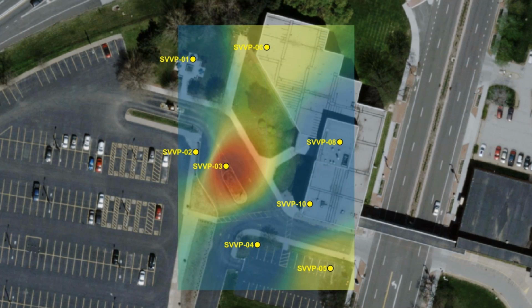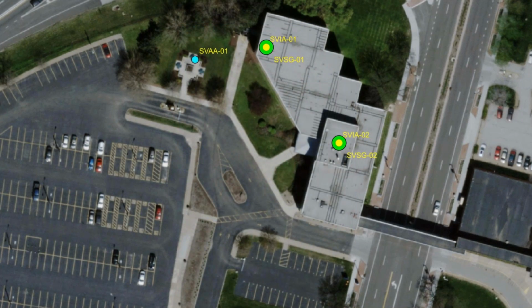They decided they wanted to collect some indoor air samples paired with sub-slab samples. So we went back in and we collected a few in some areas that looked to be of interest. We also collected an ambient air sample, which is very important so you can understand what's coming in from the ambient air. And what we found is that this was a good buy for them. The inside of the building was not affected, but they should be careful out in the parking lot.